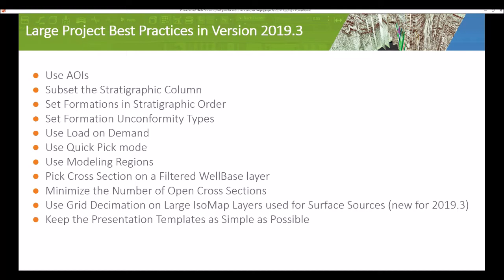Keep the presentation template as simple as possible. Complex presentation templates take time to generate in a large cross-section. Keep the presentation template as simple as necessary for interpreting your cross-section, and your cross-section will generate and display faster.